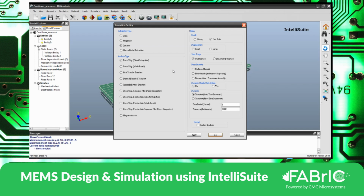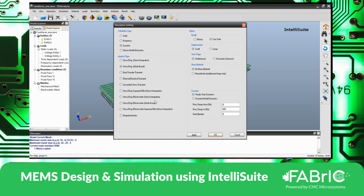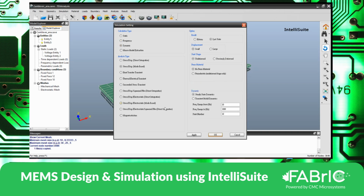And in the case of dynamic, we have two options, whether we want to operate in the frequency domain or in the time domain. So here we have direct integration as time domain, and mode based as frequency domain. The simulation that we did with frequency simulation is also related to dynamic here, because here it's a time response. The frequency gives the value. The dynamic analysis gives us the plot.